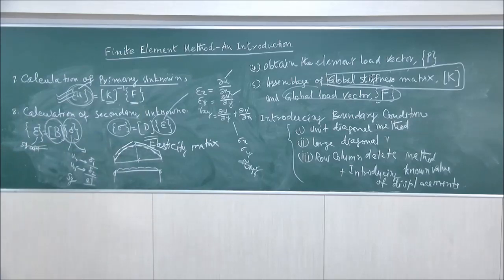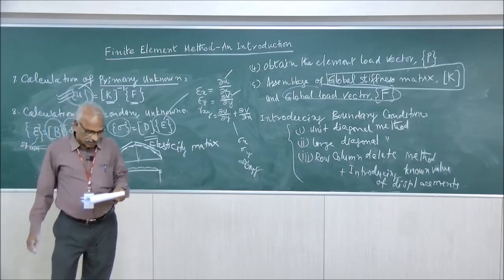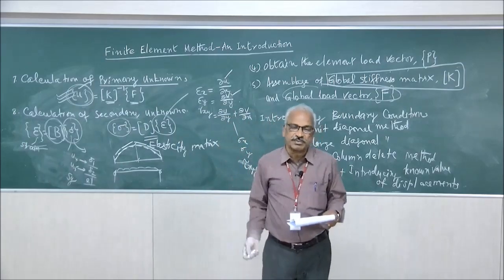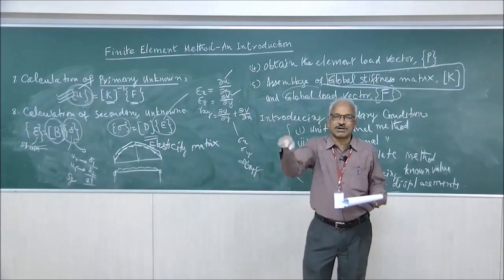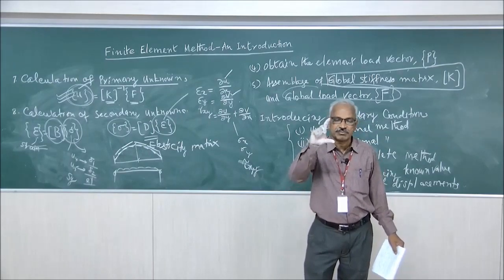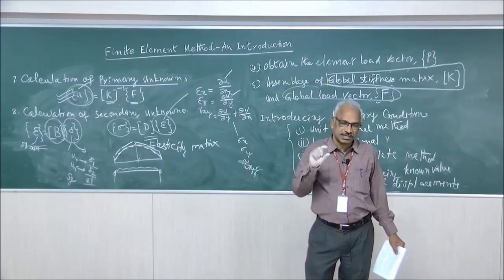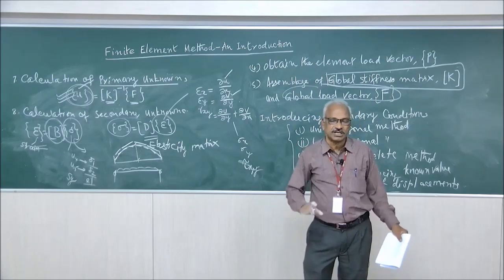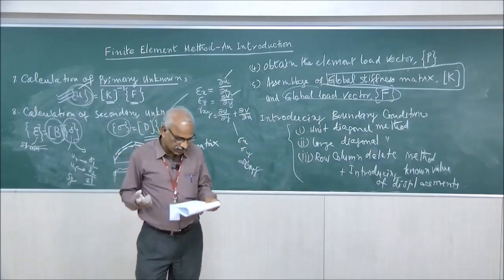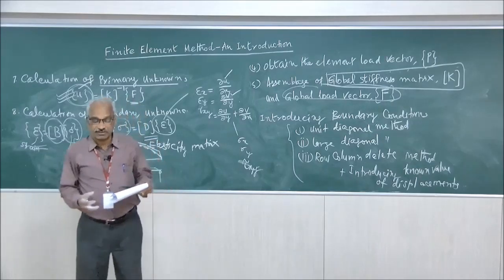the points are, the finite element method is advantageous. You can incorporate many different properties for each element. You consider a triangular element, it can be of 3 or 4 different materials, maybe 100 mm thickness, the first 20 mm may be one material, the second 30 mm may be a different material, third layer, fourth layer. So, for each and every element you will be able to incorporate different material properties. So, that is one advantage.